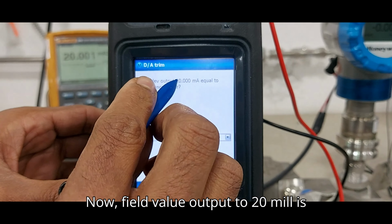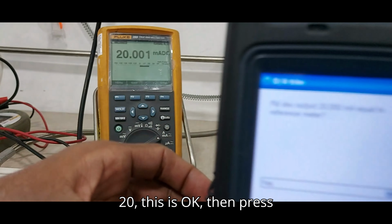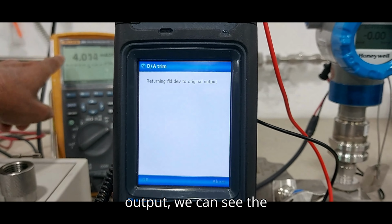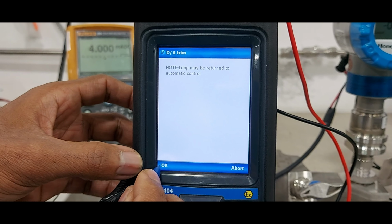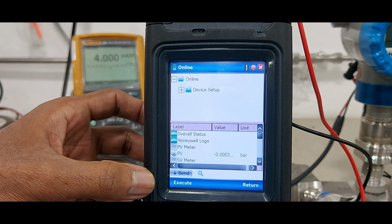Now the field value output of 20 milliamps is equal to the reference meter, 20. This is OK. Then press OK. Return to the original output. We can see the reference meter. Then press OK. DA trim calibration is completed.